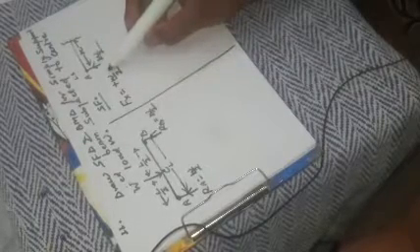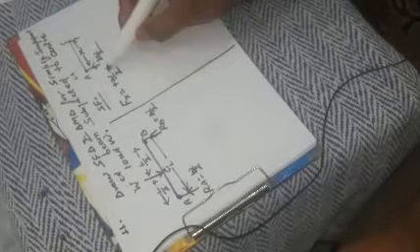In sign convention, when we are considering left segment, upward forces are positive, right? Fx equal to W by 2. Now, this expression W by 2 is independent of x. It does not depend on the position of cross section, but we can write here x to the power 0.